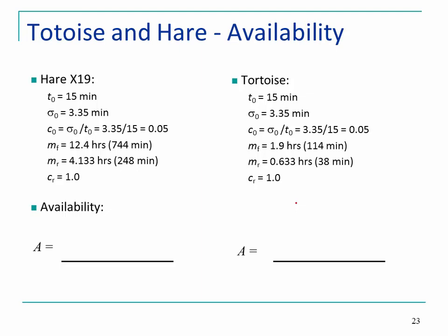Now, if you look at the mean time to failure and mean time to repair, as we mentioned already, this one is going to have longer periods of time without the failure, but the time for repair is going to take longer. And this one will have failures more often, so it's happening every 2 hours, but the repair time is also low.